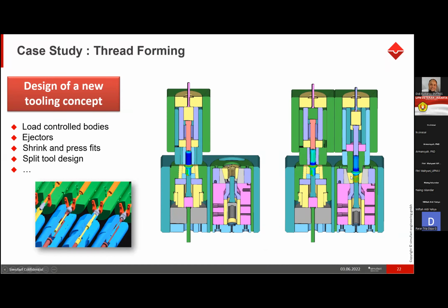Here, not only a planar motion, you can also create this wedge-type motion die. You can see the yellow one is initially on the top, now it is at the bottom, because there is a deformation. The green one will be pushing it down, and the wedge will be moving in the inward direction. So like this, as I mentioned, there is no problem with tool kinematics. We can really address the tool kinematics very well.